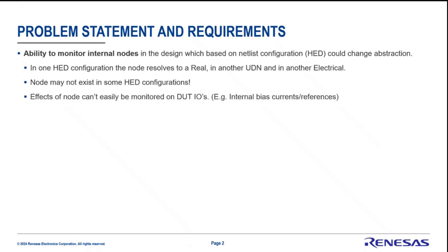So if we take a classical chip, it could be there's some internal reference. That reference could have a big kick on it, but you can't see the effects of that externally because the analog control loops, etc., mask the effects. But actually, that kick is important. You need to see what's causing it, when it's happening, to root cause the problem and also fix it.